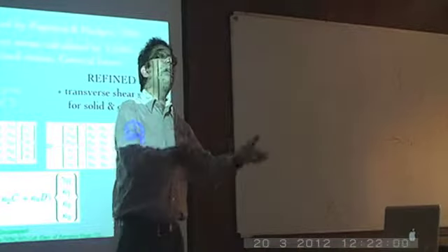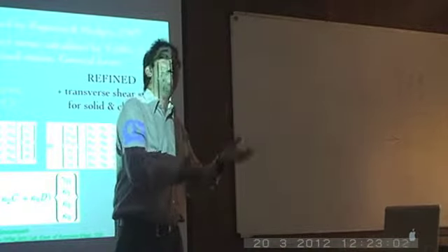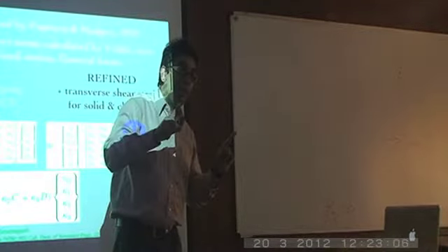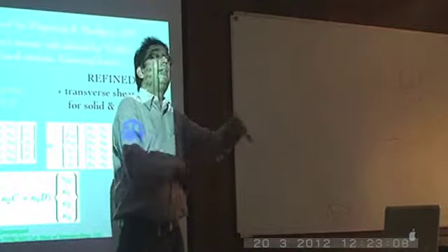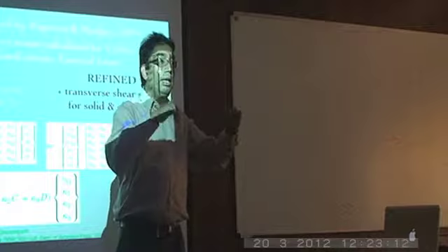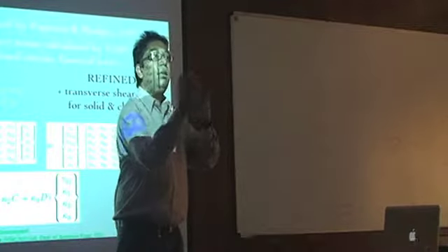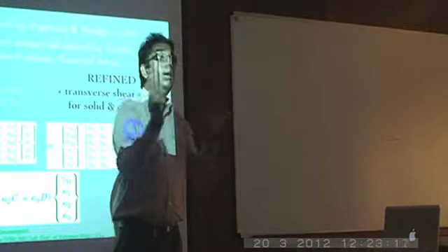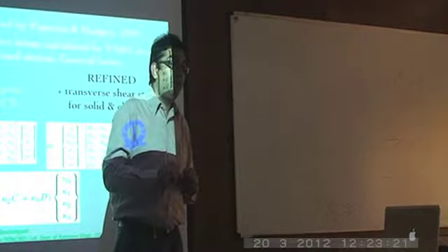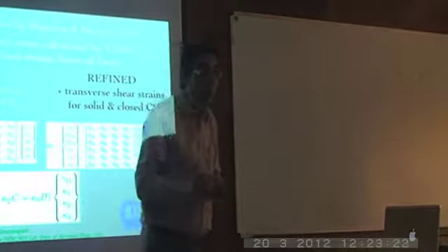So basically the nonlinearities which are going to come because of that are going to be much more important than any transverse shear effect for thin plates. But if you go for thicker plates, the transverse shear effect will come before the nonlinear effects come into the picture, because now the bending curvatures will be fairly small, and the twisting curvatures of a plate will be fairly small if it's a thick plate. Which law will follow for those thin plates?